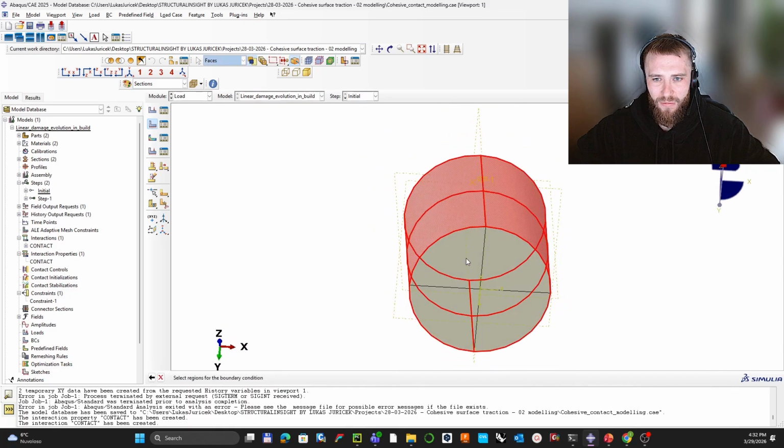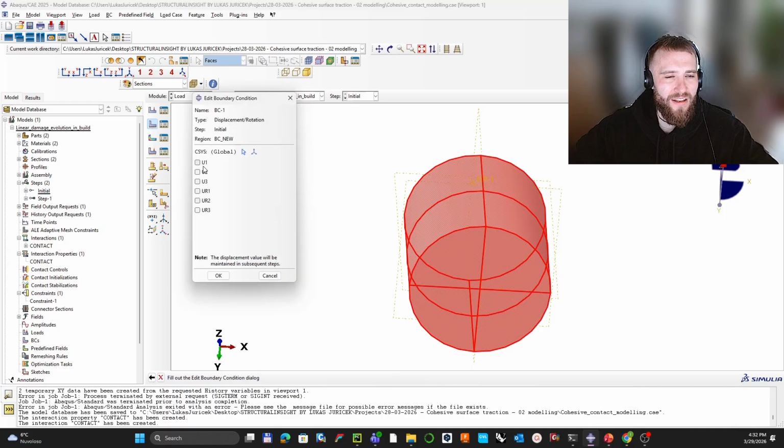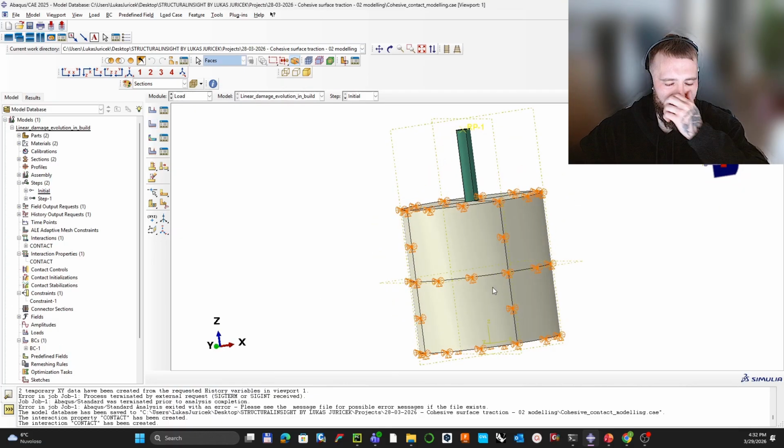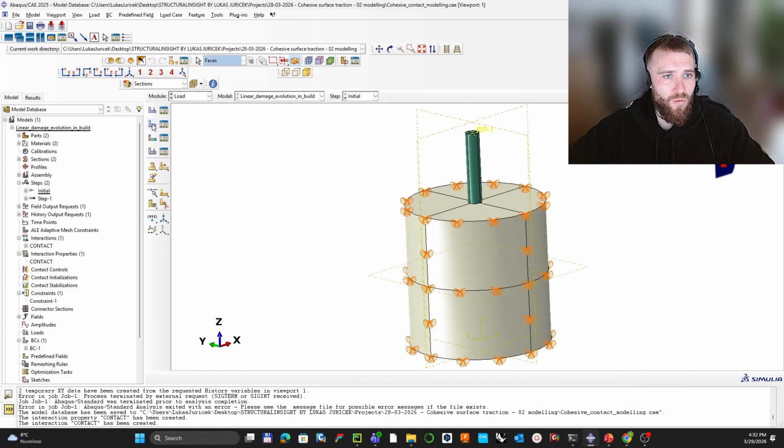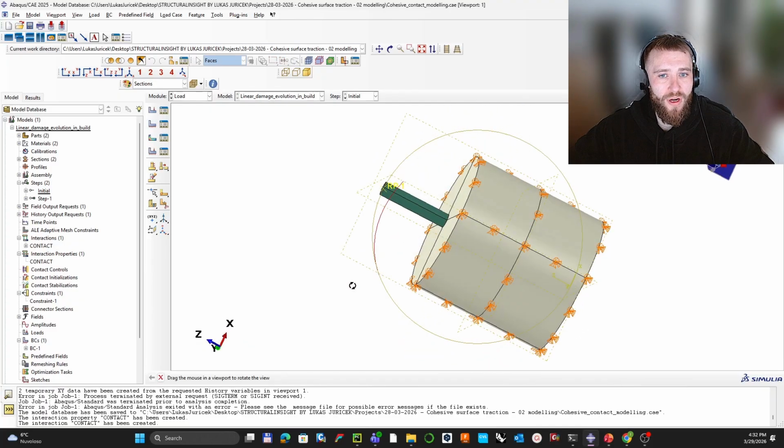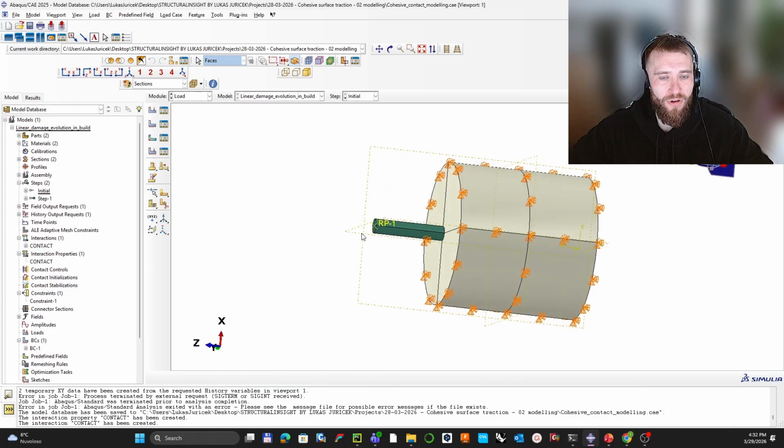Okay, and in the bottom. Perfect. I will just confirm and select U1, U3, U2 because there is just a solid element that has just the translation degrees of freedom. Actually, I need to just move to the definition of the deformation.